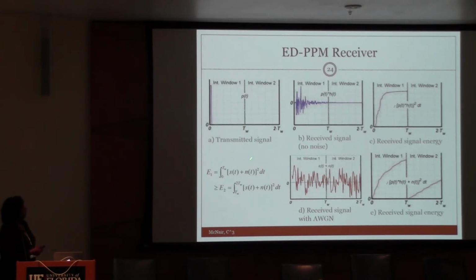The operation of the scheme is to take a transmitted signal 1 or 0 and label it by the pulse's position. So a pulse transmitted in this first window received would be labeled as a 0, for example, and a pulse transmitted in the second window would be labeled as a 1. So each bit that's transmitted takes up this 2 TW, or this transmission window, for that one data bit.